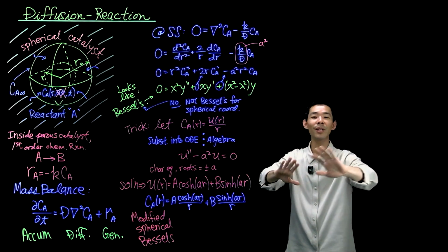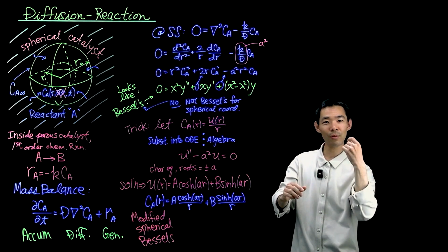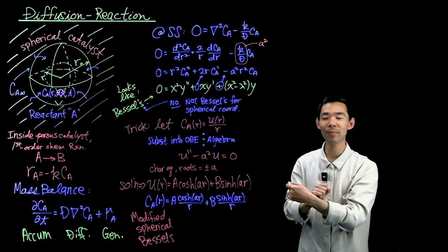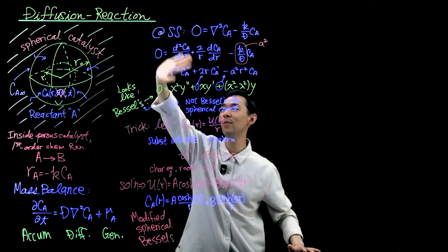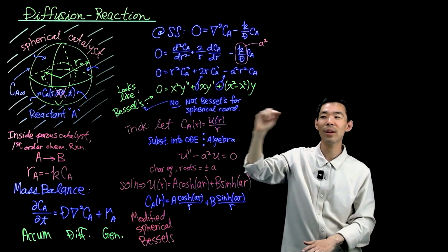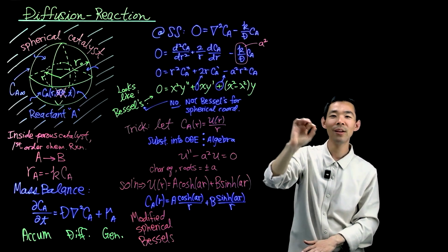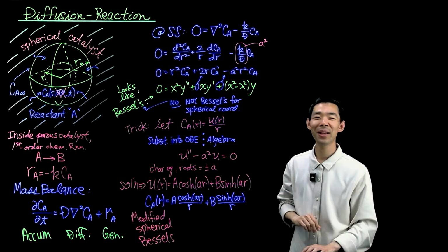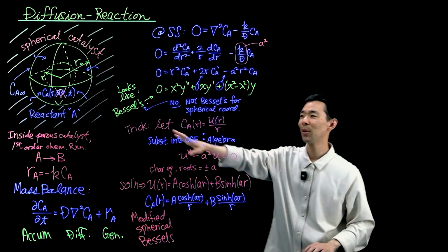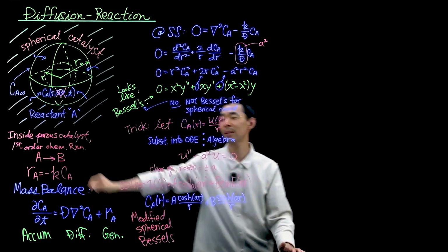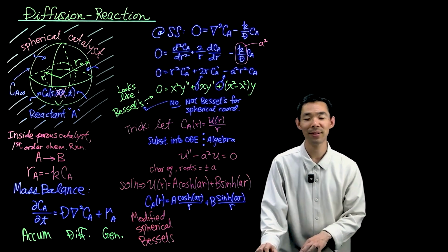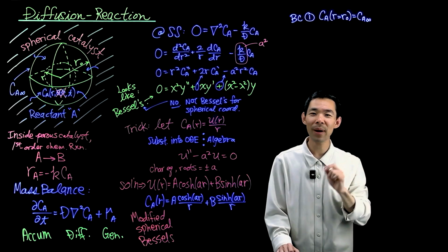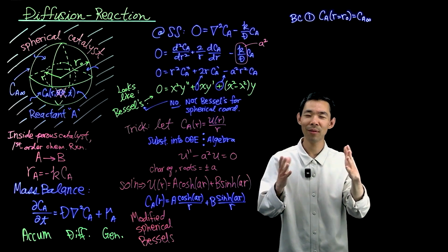But we're going to ignore that because there's a stirring rod in there. It's infinitely mixed. It's a high Reynolds, high Peclet number problem, and therefore the concentration infinitely far away is equal to the concentration right up to the surface. You're going to learn all these things in your later classes in chemical engineering, but for now, simple case. We're given the bulk concentration right at the surface. Let's write that boundary condition down. Just like that. Well, we now need a boundary condition where?